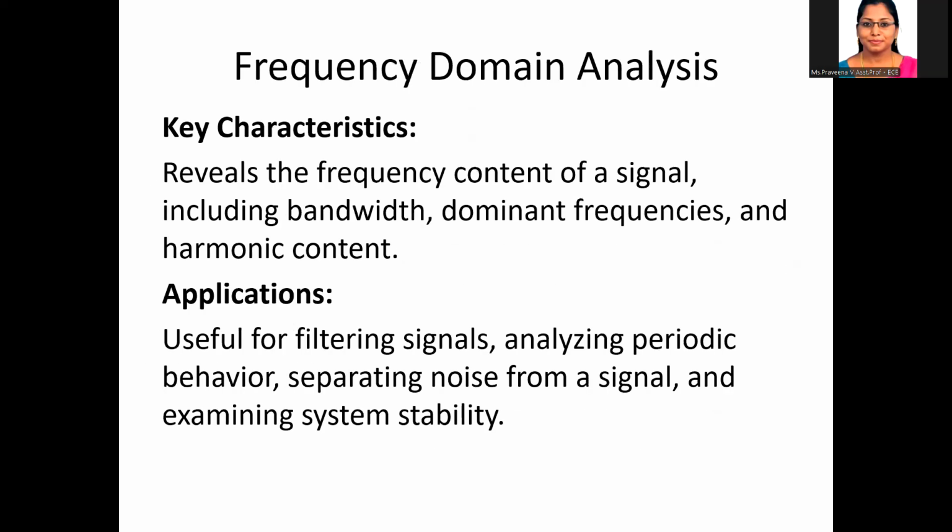Then there is frequency domain analysis. Frequency domain analysis studies the frequency components, that is, how the frequency components are present in a signal. The main focus is the signal amplitude. If you plot a graph, frequency is on the x-axis and signal amplitude on the y-axis. That is the main difference between time domain and frequency domain. Then we can calculate the performance of the system at different frequencies.